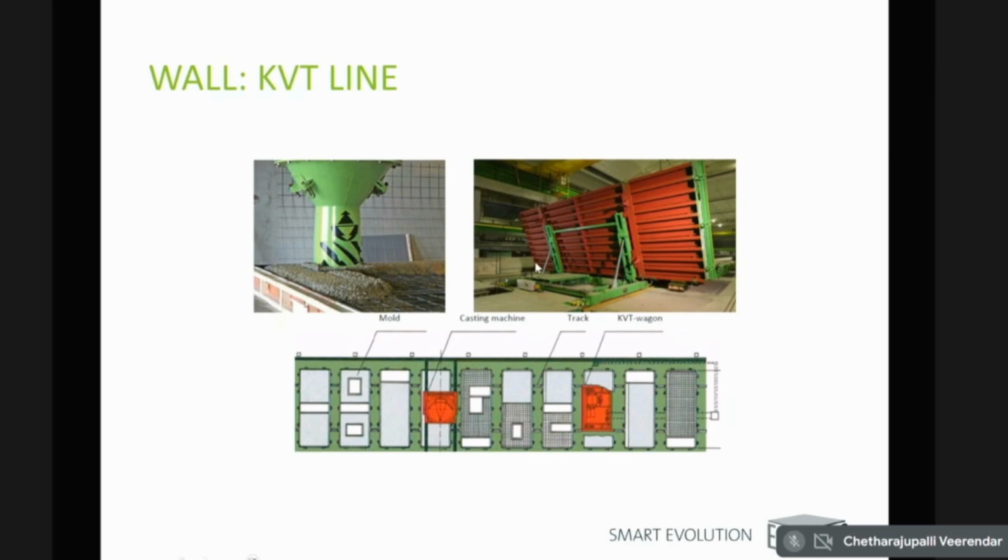And you can see here the wall production system. The wall production system has got a concrete casting on the table, and you can see in the picture here that you have different elements casted here. These are 2 solid walls. This is 2 window openings, and here is a solid wall, which is a long wall. And then you have here door and windows. Window here, some of them are showing only reinforcement, right?